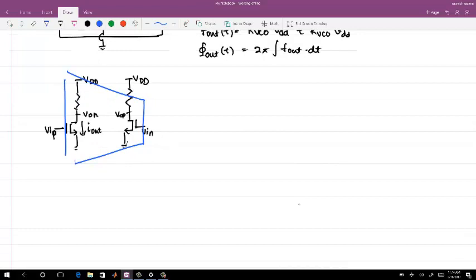Now, if this whole cell becomes one single cell and is cascaded, the common mode of each cell is getting shifted, and every cell is getting shifted. It might be consuming more current or less current, depending on how the common mode is getting shifted. That is in a zero differential case, right? But in case I have a fixed current source, what will happen? Nothing. If VIP and VIN shift by the same common mode voltage, this potential will get shifted.